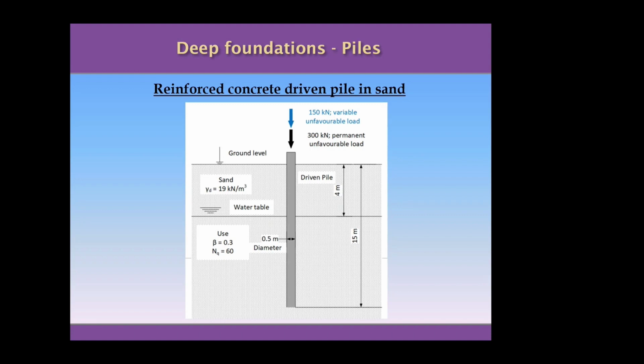And on the other hand, even when you have only one soil, let's say in this problem we have only sand as the only layer of soil receiving the pile, the water table will divide the soil in two areas, so in two layers. A first layer on top with the sand dry, and another layer of soil that is submerged in water, so it's saturated. So this will distinguish two areas that will work differently. So you will need a dry unit weight for the sand and the saturated unit weight for the sand as well to resolve the problem.